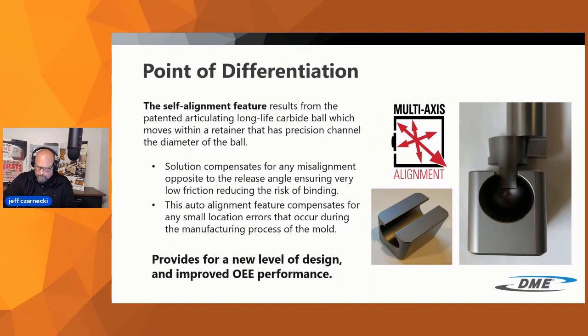Depending if you stick with a round rod as you make or produce a custom lifter head, we offer a grommet that allows the head of the lifter to float. So through the injection molding process, as you have thermal expansion, or even in the build process, if you miss a tolerance, this system will auto align and prevent itself from catastrophic failure.